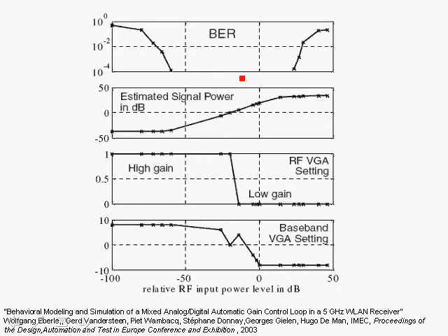Throughout this process, the actual gain at the RF is being reduced, and the gains in the VGA are being changed in order to meet the target RMS value, in order to achieve our bit error rate performance requirements.